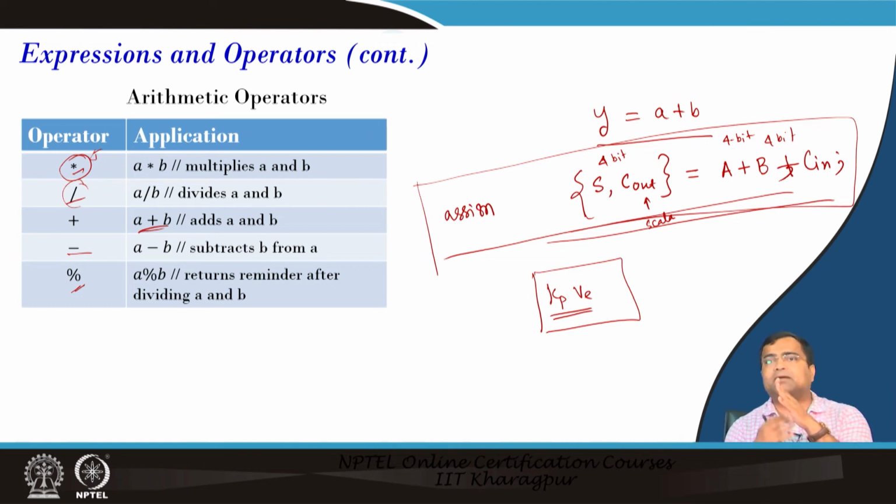Then you can speed that up and do parallel processing very fast. Most ARM processors use the RISC architecture so that you can do pipeline operation, breaking it into a larger number of smaller instructions, so that you can reduce each instruction cycle and increase the throughput by parallelism.